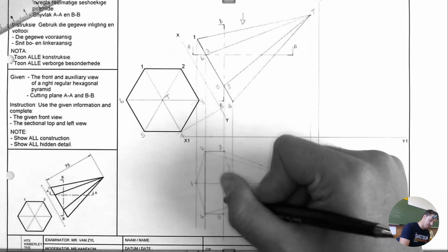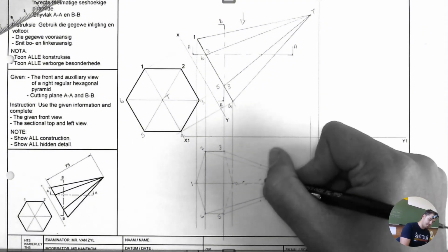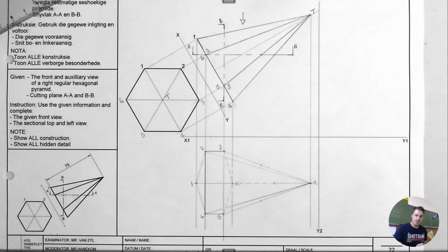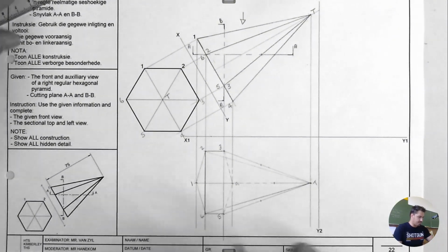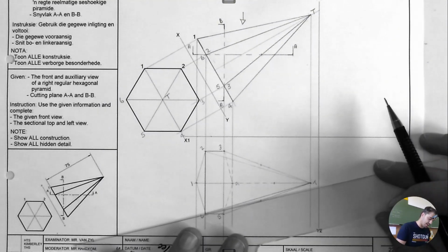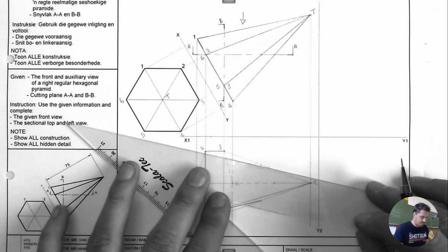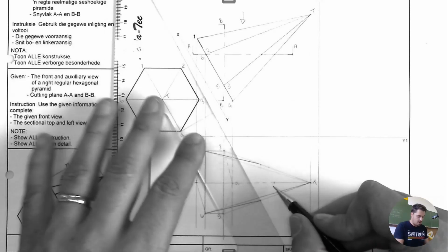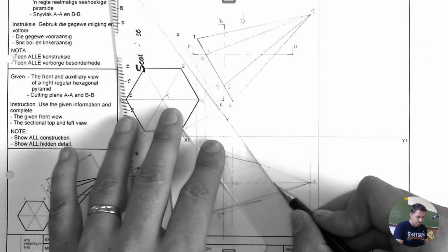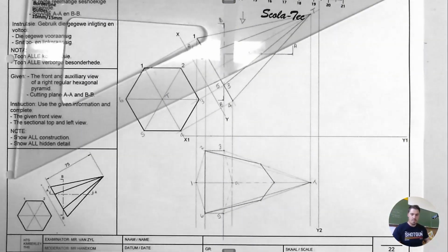and remember, usually you do this beforehand, you work it out. It makes your life a bit easier. So here you can see the hidden detail. I've only drawn it up to here because once you have your cutting plane and you've indicated your cut, you can connect the dots together. Right? So this point goes back to there. This point goes back to there. Alright, so that is the form that the cut is going to take.